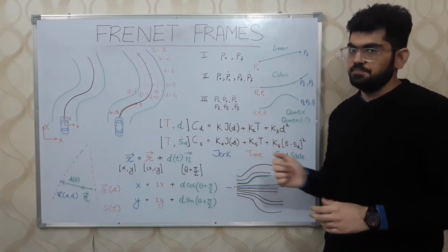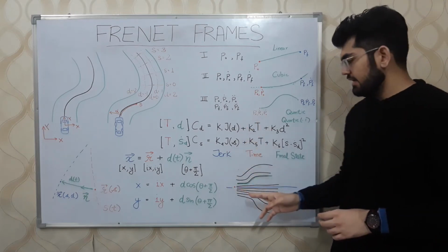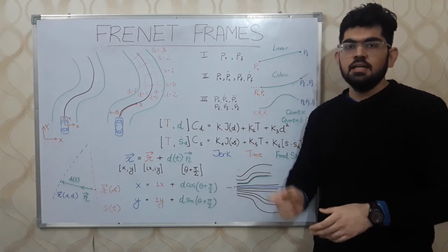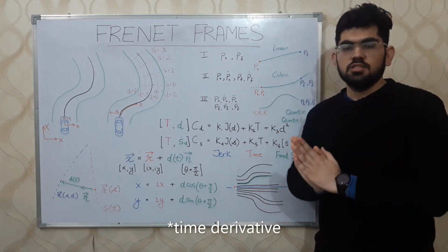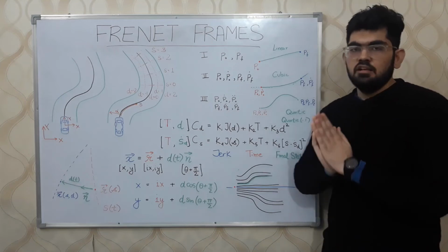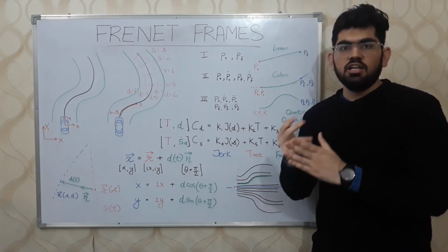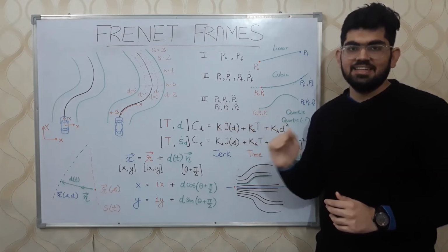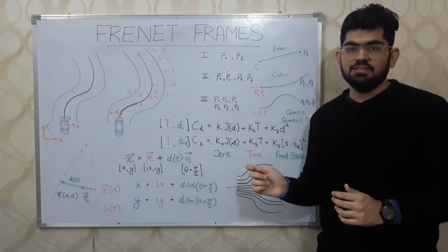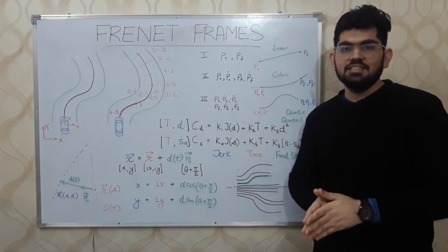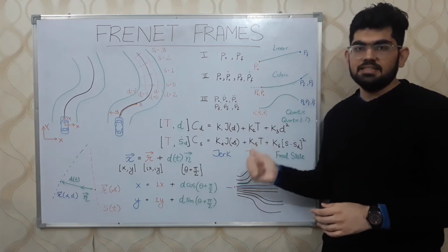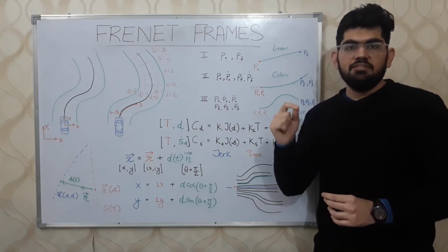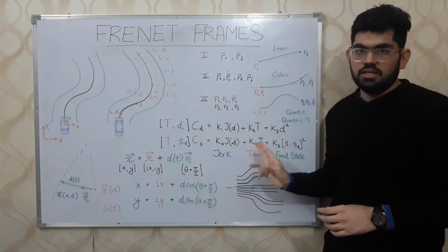We have three terms. The first term is the jerk, the second term is the time, and the third term is the final state. Mathematically, jerk is represented as the triple derivative of position, which is also the derivative of acceleration. Physically, jerk represents the ease or comfort that a person has while sitting in a car. If we have sudden accelerations and decelerations, it would not be comfortable for any person sitting inside the car. Minimizing the jerk smooths this behavior, hence we have this present in our cost function. We also need to minimize the time it takes for the car to follow a given trajectory, hence we have this time parameter over here as well.